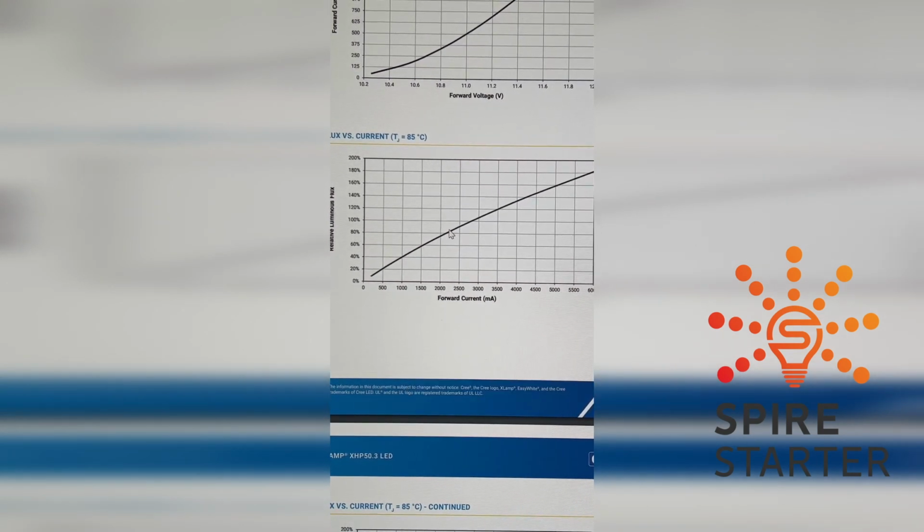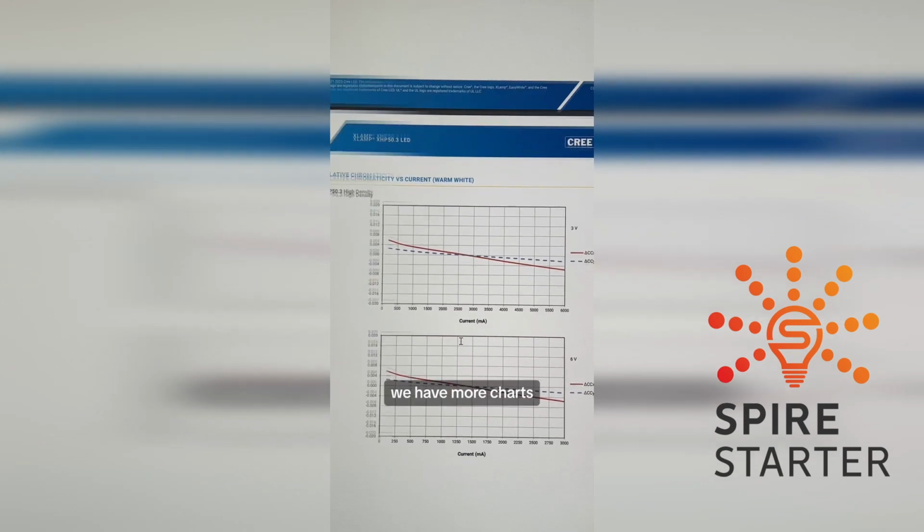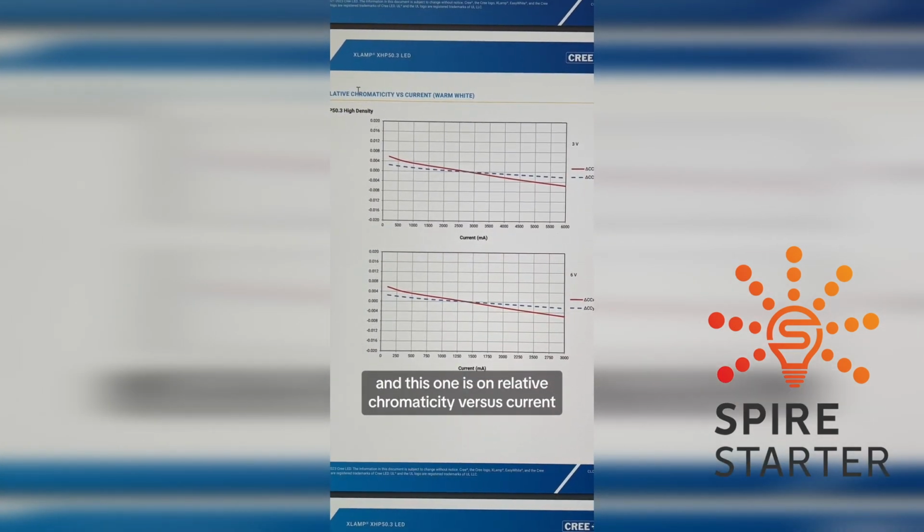And that's why you want to design your system around 100%. And if you actually need something way lower or you actually need something way higher, then you want to pick an LED where that neighborhood is where that nominal is going to be. Usually you're only going to see competent hardware design use this high end of forward current if it's like flashing, strobing the LEDs. Scrolling down, we have more charts, and this one is on relative chromaticity versus current.